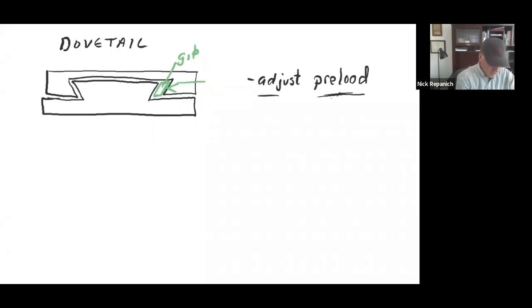So when you put this in with these little divots, this would go in like that, and then this would get assembled. There we go, like that. So now we would have a bearing with sliding friction and adjustable preload. That's good. Adjustable, we could set these in. So why would you ever want to do this?